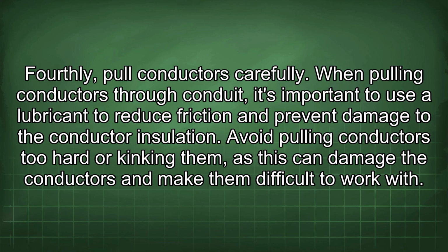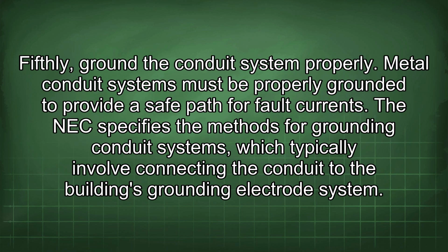Fourthly, pull conductors carefully. When pulling conductors through conduits, it's important to use a lubricant to reduce friction and prevent damage to the conductor insulation. Avoid pulling conductors too hard or kinking them, as this can damage the conductors and make them difficult to work with. Fifthly, ground the conduit system properly.